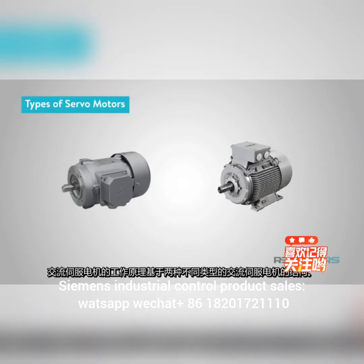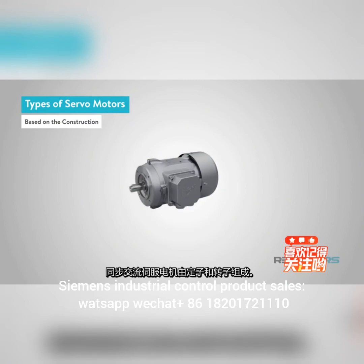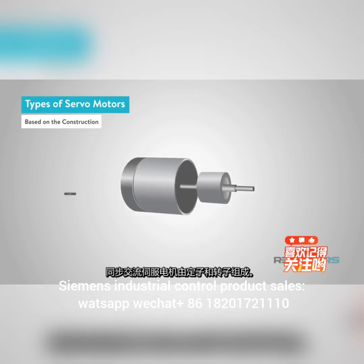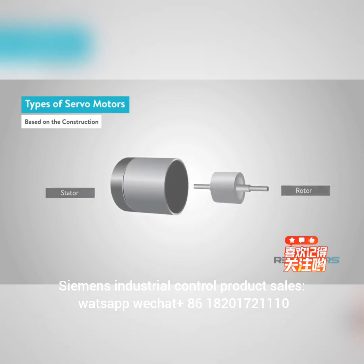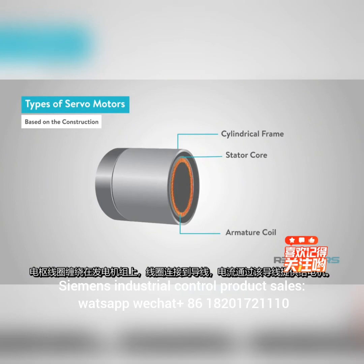The working principles of an AC servo motor are based on the construction with two distinct types of AC servo motors. They are synchronous and asynchronous, or induction. The synchronous AC servo motor consists of a stator and rotor. The stator consists of a cylindrical frame and stator core. The armature coil is wound around the stator core, and the coil is connected to a lead wire through which current is provided to the motor.